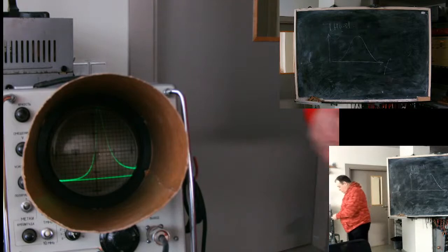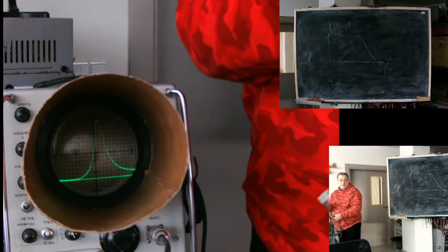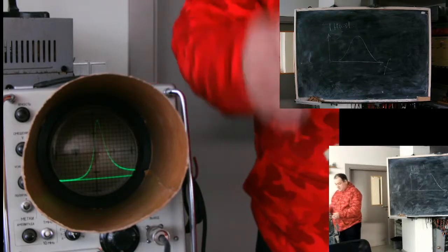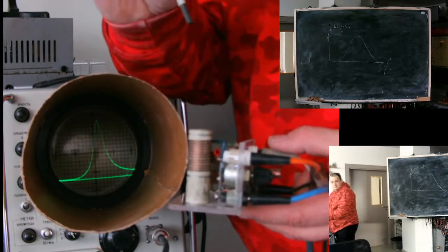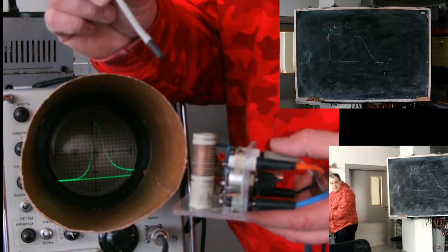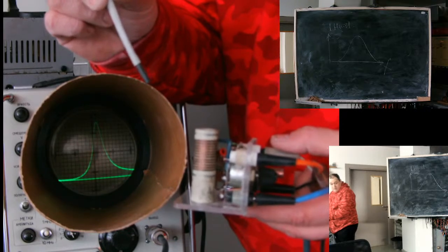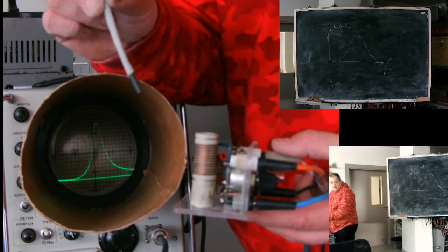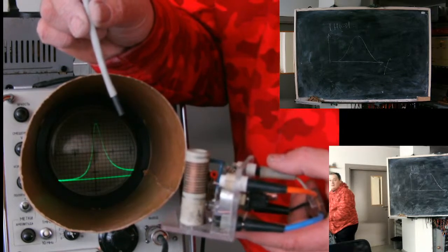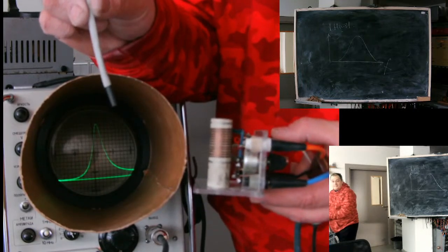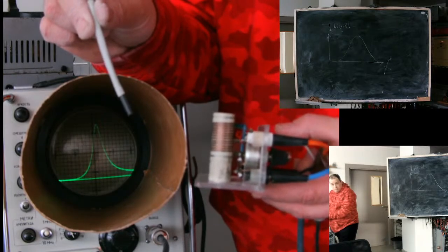I have two small bars. Which one? This one. It's a ferrite. Material with a good magnetic conductance. What will be the effect if I introduce it to the coil? Magnetic conductance increases. Yeah? Inductance also increases because the coil can store more magnetic energy. More magnetic energy means more inertia. More inertia means higher or lower frequency? Is it easier to push something heavy?